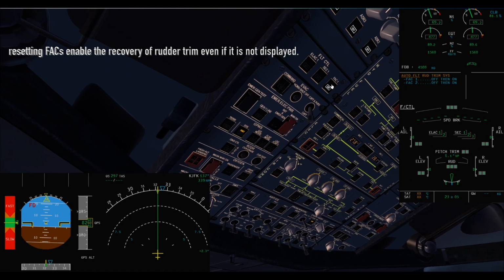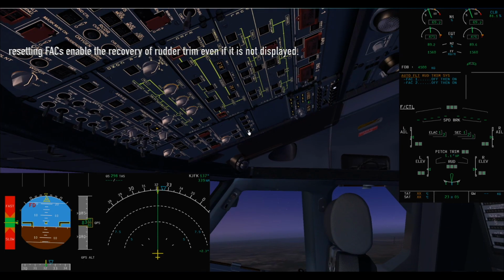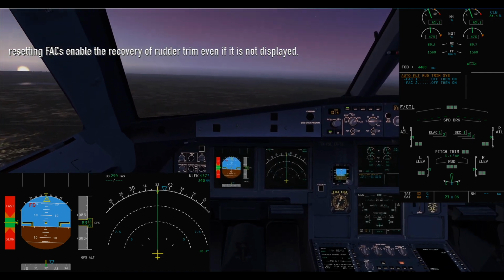The flight augmentation computer controls rudder trim and yaw damper inputs. Here, the aim of resetting these computers is to enable the recovery of rudder trim even if it is not displayed.